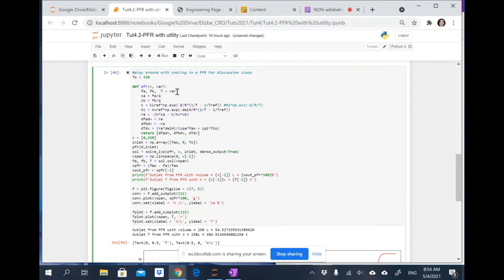In many liquid phase reactions, you don't have to model all the components in order to answer the questions that are asked. But in gas phase reactions, you need a mole balance for each of your components because the total molar flow rate must be used to calculate your pressure drop. So if that was confusing you, remember our reaction is just an isomerization reaction. So A just goes to B. Right, so there, that's comments. A just goes to B.